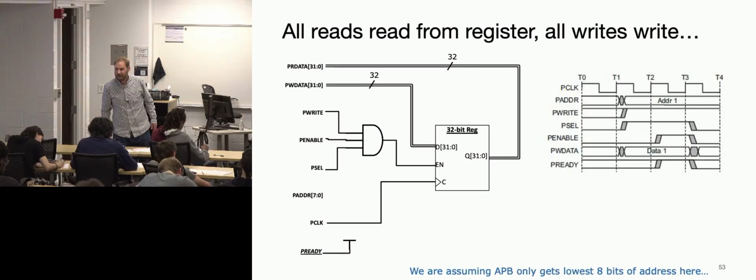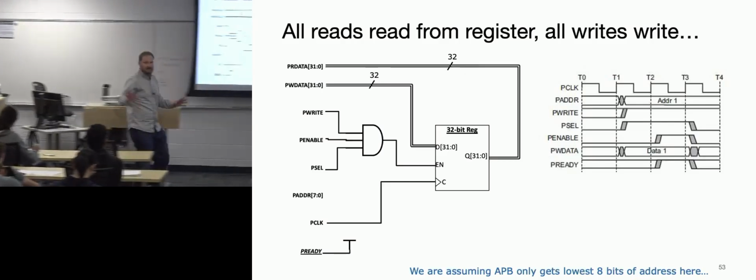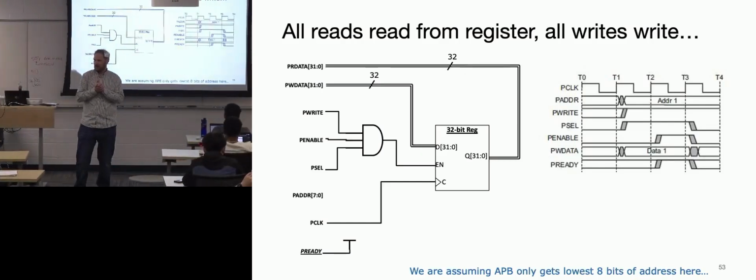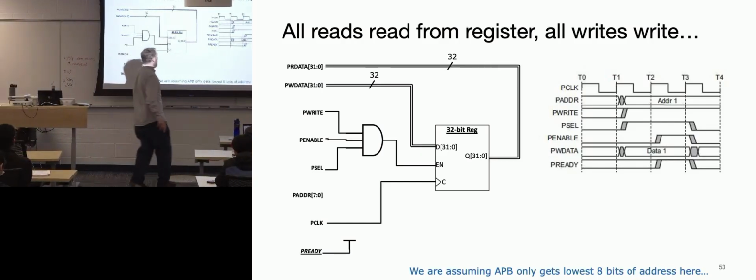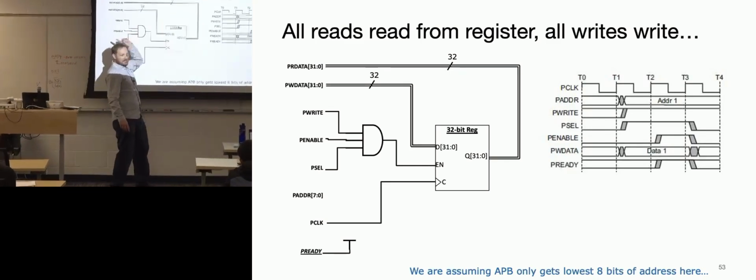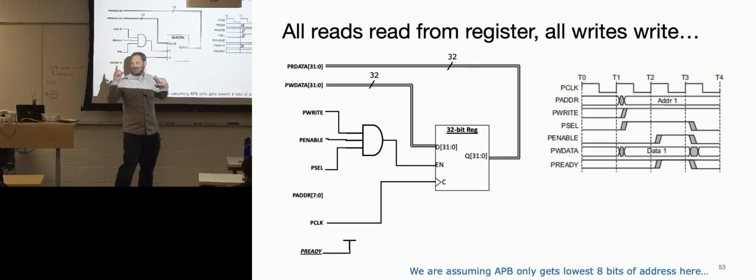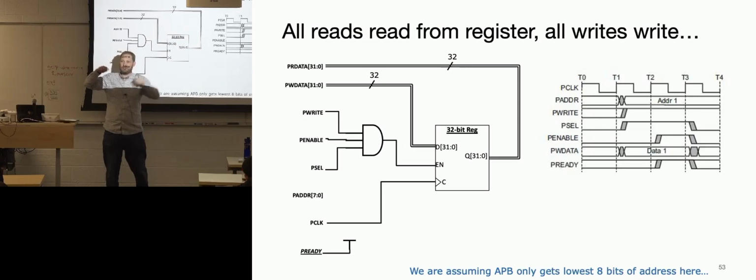Additional information for read data based on addresses, because we don't know which specific address they're going to. That's true, maybe, except I made a toy problem for you. The toy problem is this is the only thing in this peripheral, and there's a bus that goes all the way back to the requester, and each peripheral has its own bus. So now it's the requester's job to look at the correct bus.